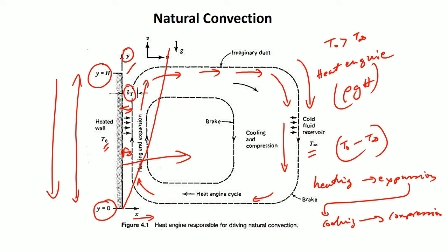because of the temperature, because you are transferring heat from a heated wall to the layer of fluid adjoining it. So, you can pretty much foresee that the temperature will be high here, and it will gradually come down to some level, correct. Outside the boundary layer the temperature will be the same as T infinity, this is your T naught, that is how the temperature profile should look like, correct. So, this is basically the temperature.